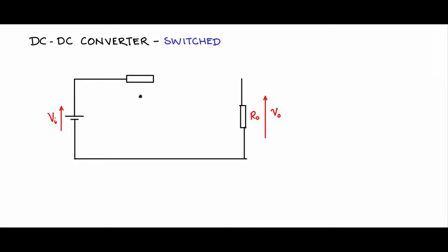In the linear regulator case, what did we do? We put a variable resistance component, which could be a resistance or it could be a semiconductor switch operated in the linear region. So basically this RS resistance was varied. So when this RS is varied accordingly, the drop across that varies, and therefore we could regulate V0. But unfortunately, there is a voltage drop across this RS, there is a current through RS, and therefore there is a power dissipation VRS into I0 happening in this resistor RS, and it is not available as useful load. Therefore the efficiency is very low.